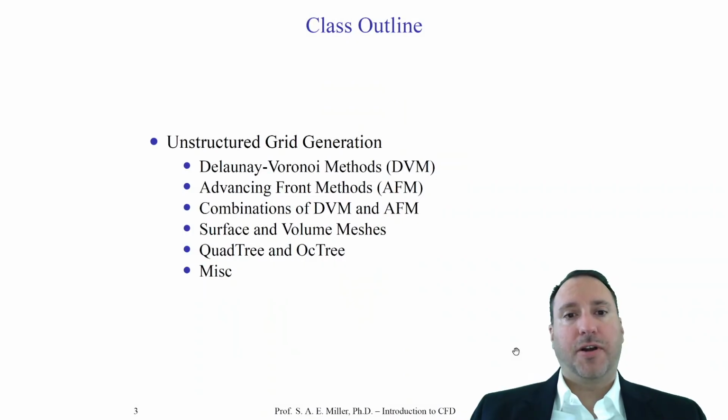In this class, we'll talk about unstructured grid generation, and we're going to focus on the algorithms of how they're created. There are no so-called simplistic metric transforms for the mesh as a whole, as there is in the structured grid approach. Instead, with finite volume, one simply evaluates fluxes across the surface of each particular volume. In finite element, each particular element is transformed into a standard element, like a tetrahedron or triangle, with the same sides and angles, and the finite element method is applied uniformly to every one. So there is a type of transform for the finite element method, essentially.